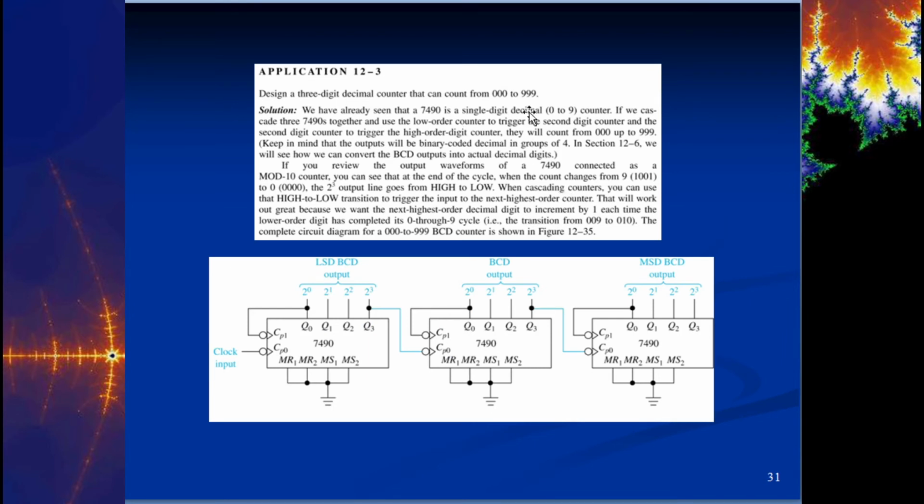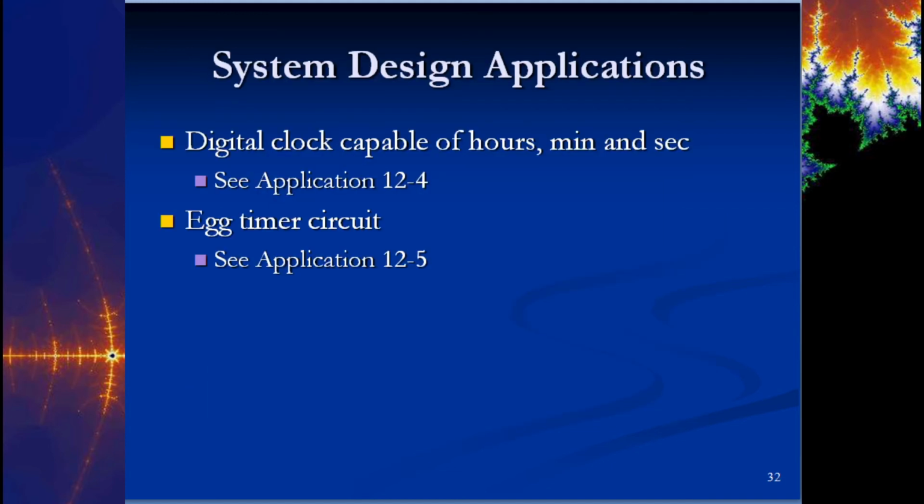Here's an example of something that goes from 000 to 999. And if you use 3 7490s, you don't have to have any reset circuitry at all. Okay. A few more of them.